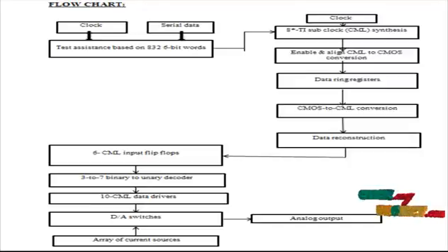In this block, 8 registers and 8 NAND gates are used to provide the sub-clock input to the next block. The serial data are given as input to this block, then the output of this block provides the sub-clock signal to activate the next block. Then the enable signal is given to this block as the control signal to activate all the registers and provide the sub-clock output.